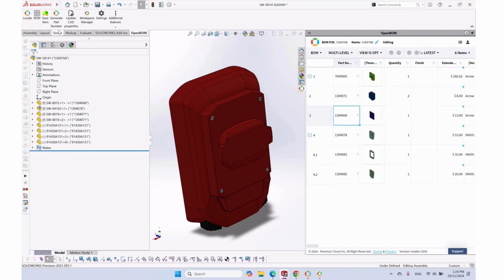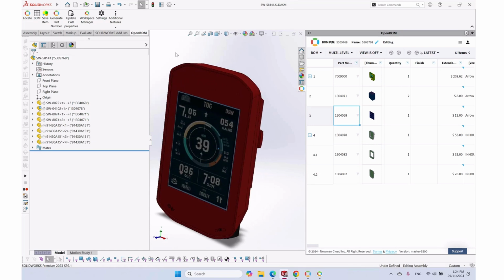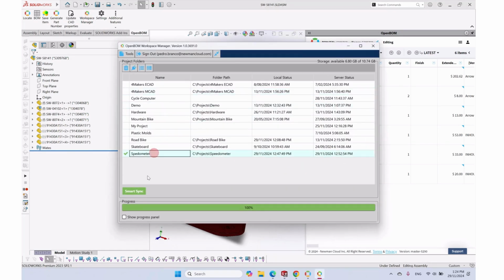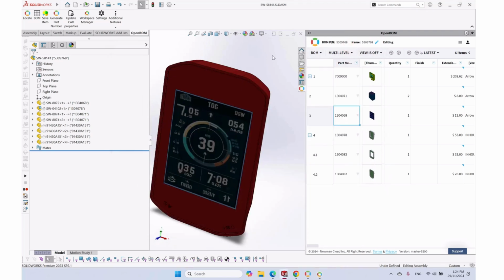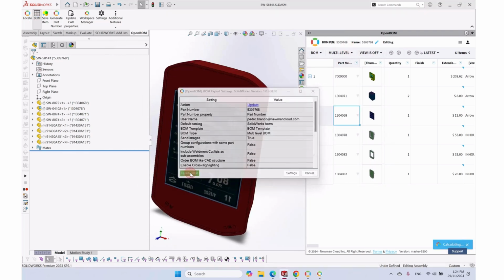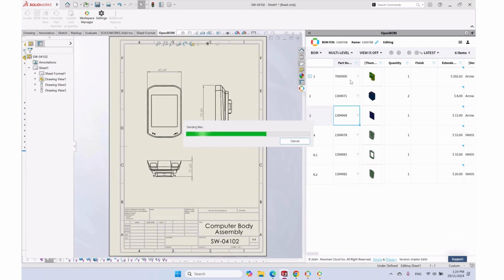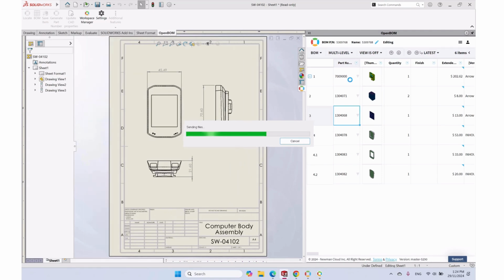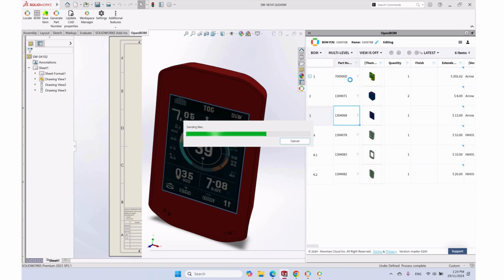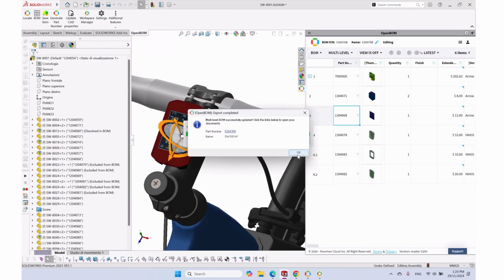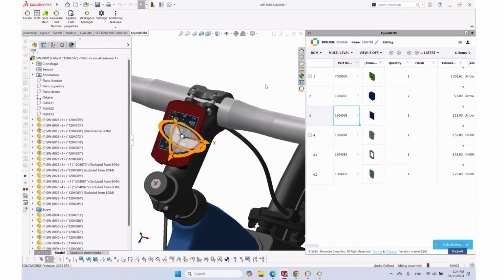We're going to save this to our CAD file. We should go through the process of synchronizing those changes back to all the users. And then we update the bill of material. So we're going to update it, and this will not remove that PCB added manually. So we will merge the changes to any other items added to the BOM. It's going to update PDFs and steps. All that will be updated. So we're going to use now a change order to release a new revision.